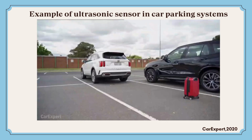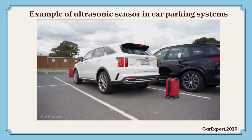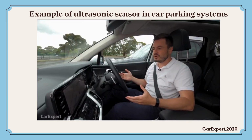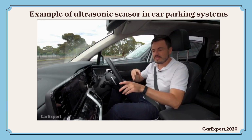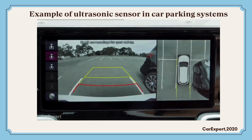Now, imagine if that was a kid or a person that's walked behind your car. It's able to use those ultrasonic sensors to detect that and slam the brakes on so you don't hit them. This is crucial technology and why we think it should be fitted to every single new car today. Now, you're wondering, where does the radar come into play in all of this? Well, an ultrasonic sensor only really works well 3 to 5 meters away from the car.